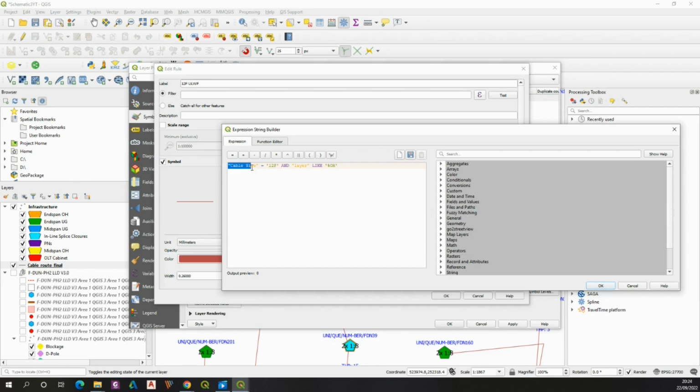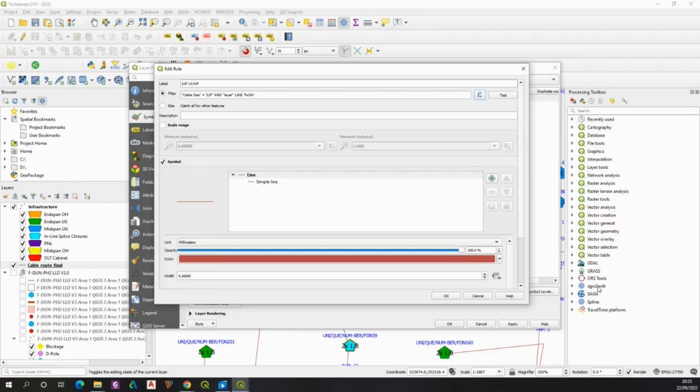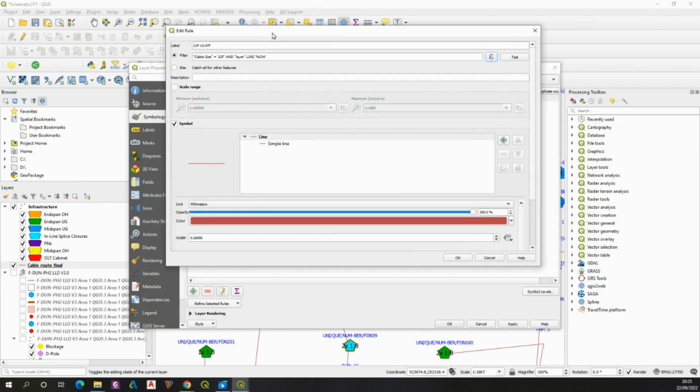One condition is the one which you can see here, and the AND statement means that both of them must be valid in order to execute the given criterion. So the cable size must be 12 fiber and the layer must finish with something like OH. As I said previously, this is the wildcard. By bounding the piece of our name within the quotes and using the wildcard, we are going to hit this condition. So now click OK, and we've got the criterion defined.